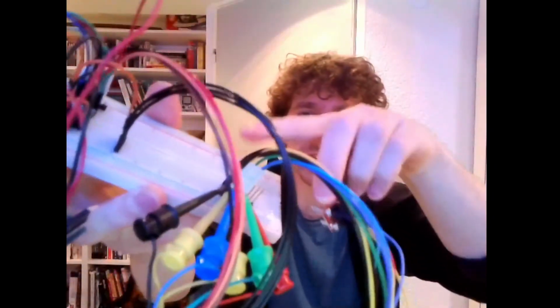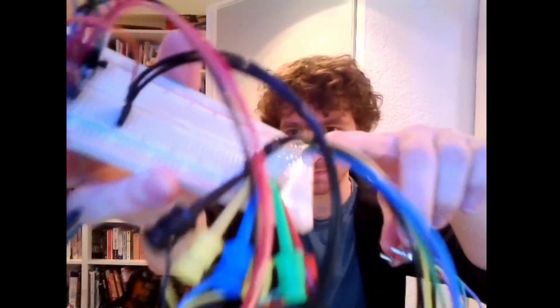Those wires go onto this breadboard and connect up here, and they're hooked up to a part where I can plug in that SD card module, and I can plug in the logic analyzer, which if you tuned in the last episode you would have seen. And I also have an Arduino hooked over here, with a level shifter, because Arduino works on 5 volts and SD cards work on 3.3.